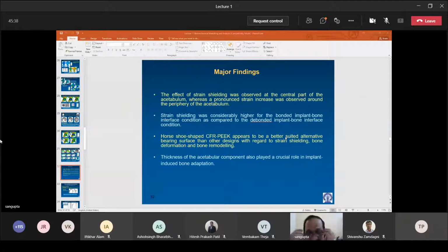So when we are validating something, we must bring them together on the same platform. Otherwise, you are comparing apple with mango. You can compare apple with apple, right? Right, sir. So the experimental conditions, loading, boundary, geometry, everything has to be exactly the same in the FE model. Then only you can compare. And that is what validation is.